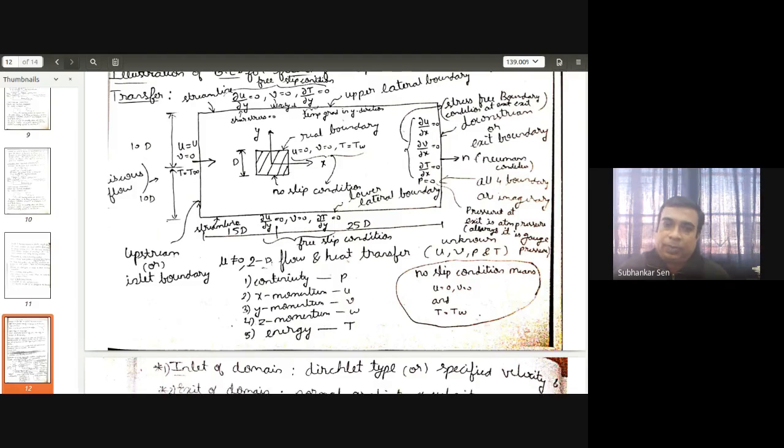At that node, you have to write these equations. So you will have many nodes. At every node, you will have 5 unknowns: density, 3 velocities, 1 temperature. So there will be 5 matrices: 1 matrix from continuity, 1 from x momentum, 1 for y momentum, 1 for z, and 1 for the temperature, and you have to solve it.